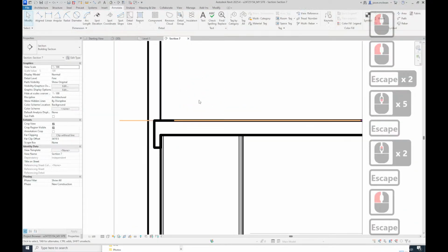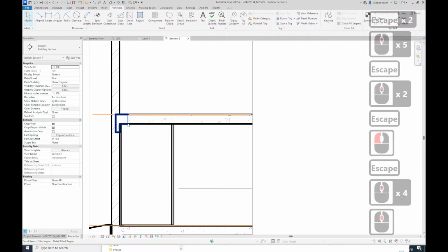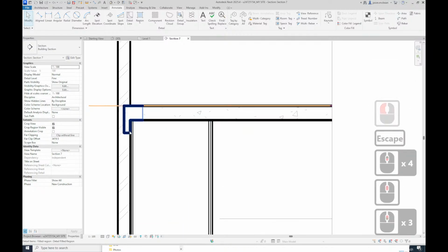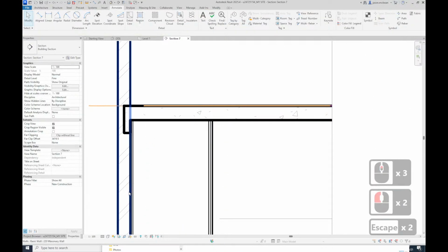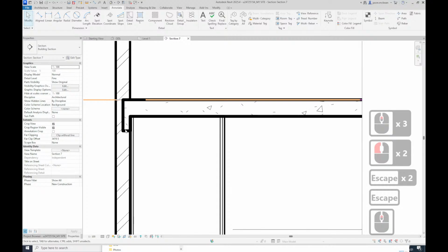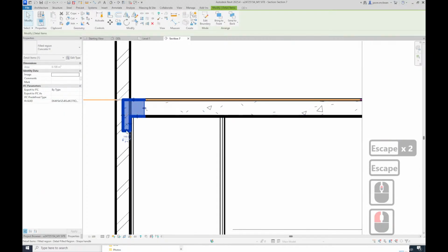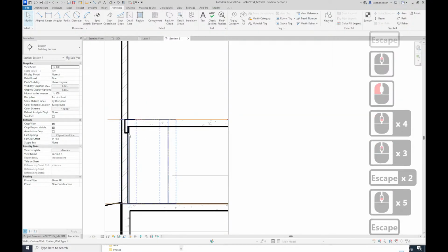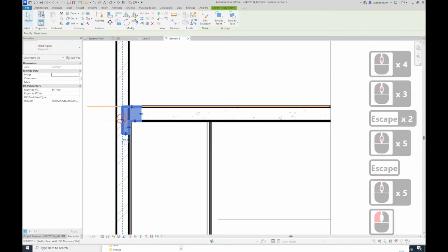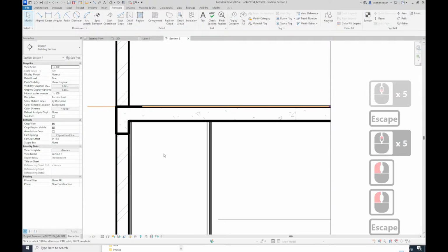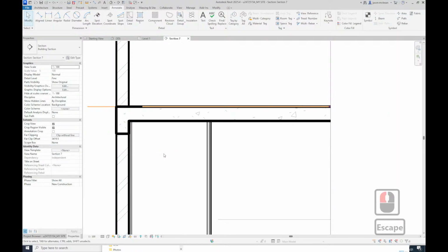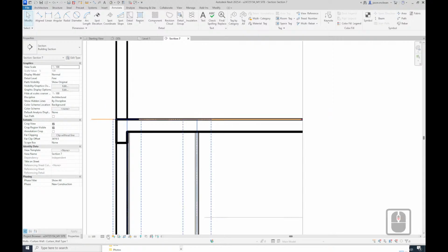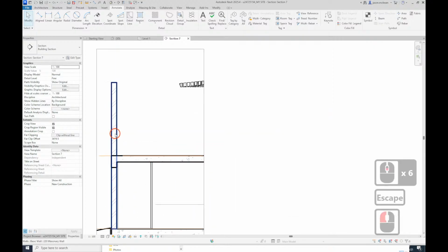So all I've done is draft that connection, how it should work. Technically, you might build a column in the wall, then you don't need a downstand beam because it'll support the slab. But technically, this acts as a beam in the wall. You can even take it through. You'll see a lot of buildings, when they plaster on the outside, have these V-joints in the facade. Technically that's a downstand beam, because remember it's carrying this whole load. So you need a beam to carry the brickwork above. So that's what the beam's doing.